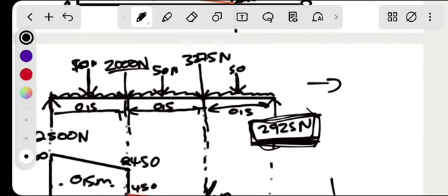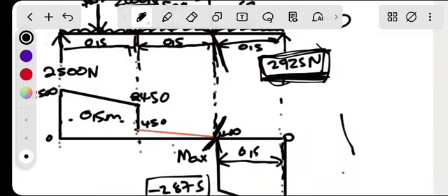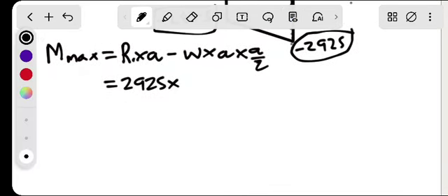The maximum, remember guys, the maximum bending moment is acting there, as you have seen. It's acting here at this distance. That means from there until where the maximum bending moment is acting is 0.5. Then I'll multiply this by 0.5. That is A. Subtract the weight, the weight of the shaft, the distributed load, this W. The weight is 100 Newton per meter.